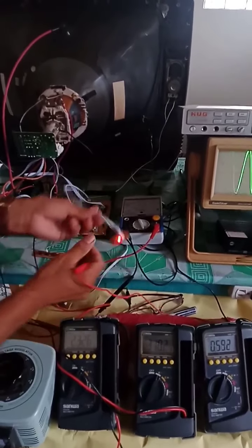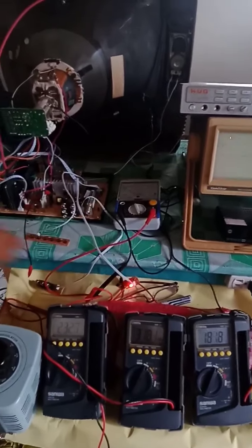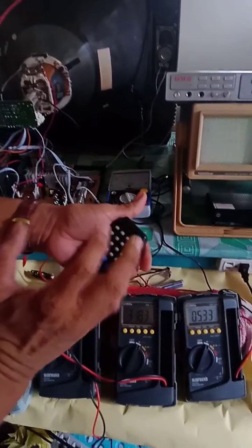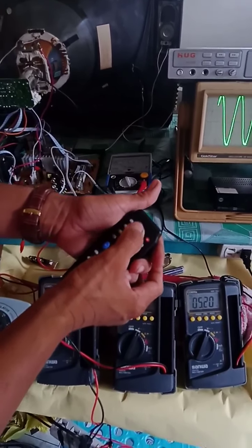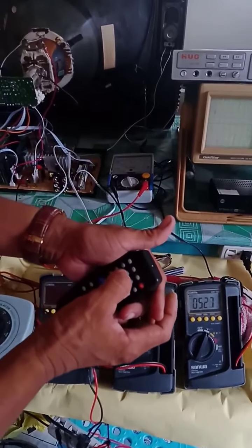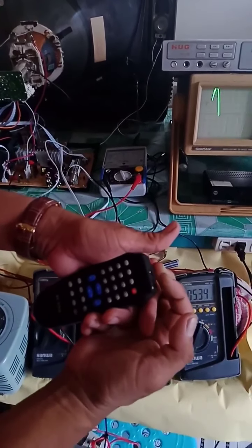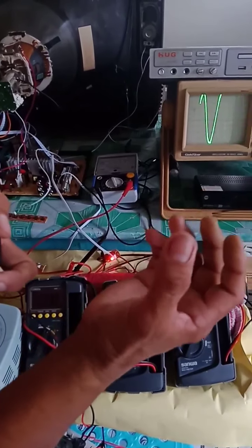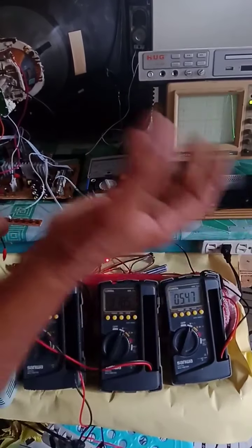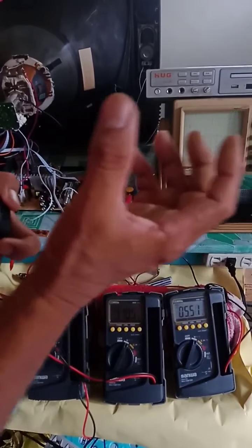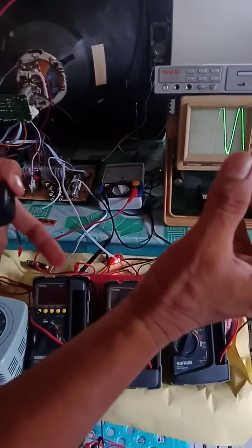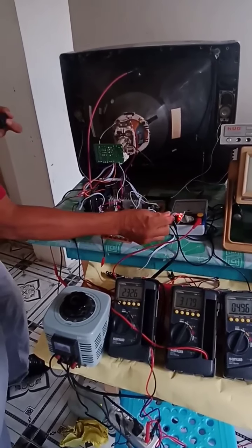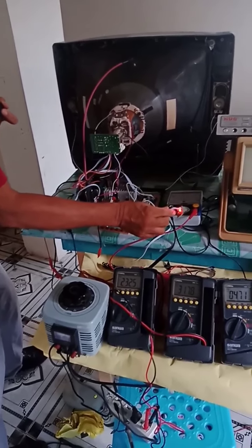Now, going back again to the infrared sensor. What is this infrared sensor, and what is this remote control? We have here a remote control. There are keys or keyboards. When you press one of these keys, the infrared LED emits light and transmits the pulses. The pulses correspond to the binary code or binary information to the TV receiver, specifically the infrared sensor.